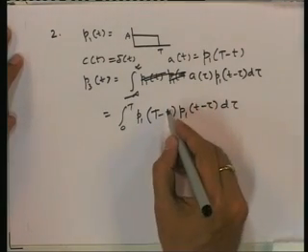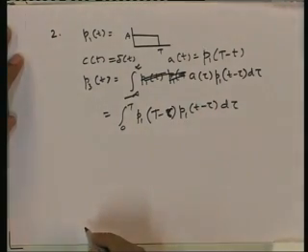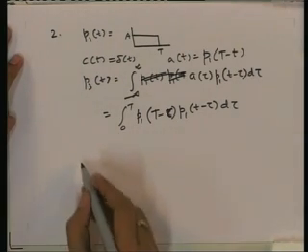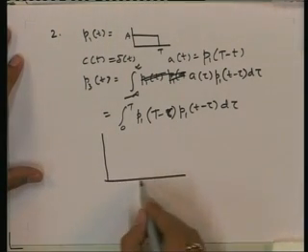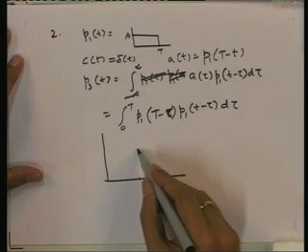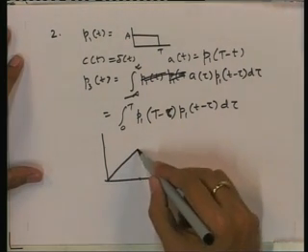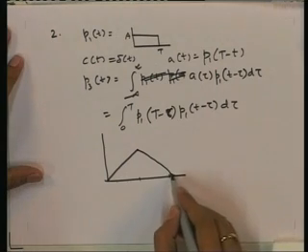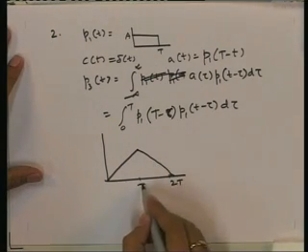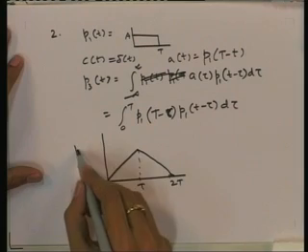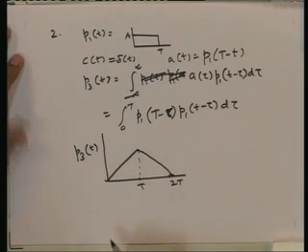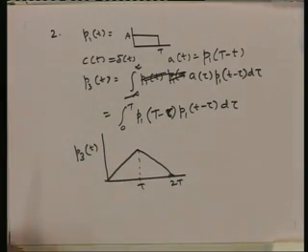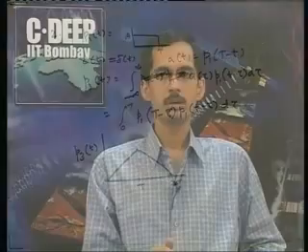So, A tau, the T will be replaced by tau. Now, if we plot this, we will see that this again becomes T, 2T, and takes its maximum value at T. It is linear, 2T, T, and gives us the maximum value at capital T. So, in both the examples we see that it is best to sample at capital T, because that gives us the maximum SNR by providing the maximum scaling to the signal part of the output signal.